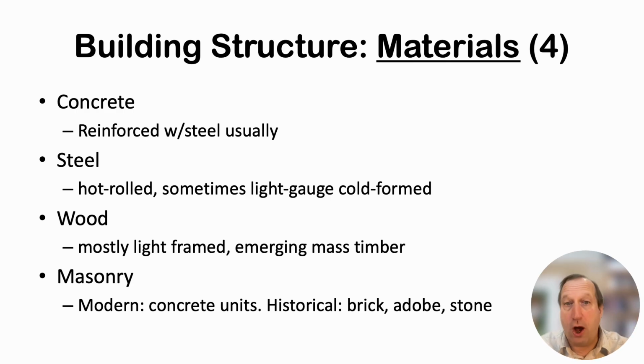We often call it concrete, where we usually mean reinforced concrete. We talk about steel. Usually we mean hot rolled steel, although, technically speaking, you could have cold formed steel. We will talk about a wood structure. Much of what is actually built as wood structures are light framing, but closely spaced, smaller elements. But that said, we're seeing a lot more interest in mass timbers, and we have a long history of post and beam and log buildings.